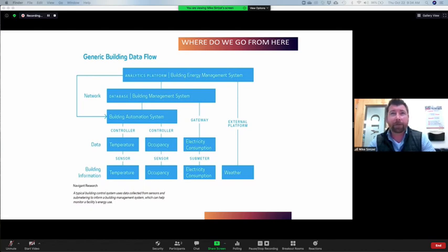With the emergence of 5G, faster data speeds will be achieved. Most devices found in current BMS systems run off older technology. So this generic data flow, some devices will actually have wireless devices. Some older devices will have newer wireless devices put on them so they can communicate with the current topologies. I think personally what we're going to see, and I would love to see, is a joining of Division 25 and 26. Division 25 is the technology spec, and Division 26 is the electrical spec.